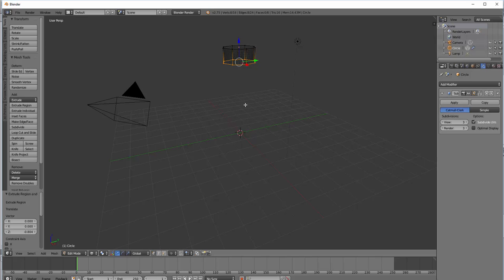Now I want to undercut this lip of the bottle, so I'm going to hit E and then enter just to create a whole new set of points that are still in place. Next I'll orbit up a little bit so you can see the bottom as I do this, and then S for scale and pull that inward just by eye about that much.